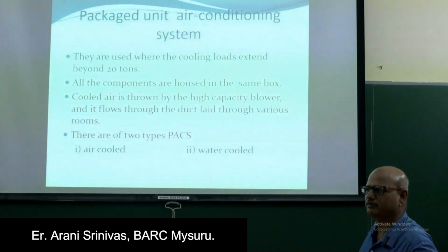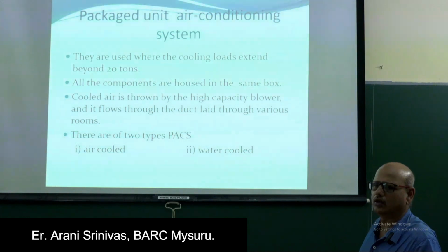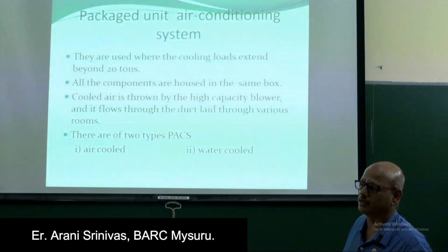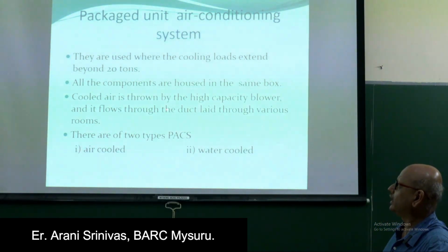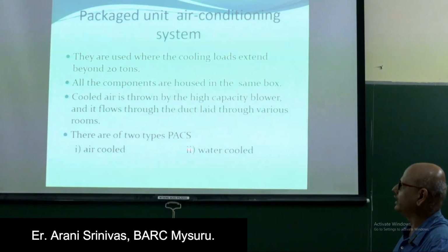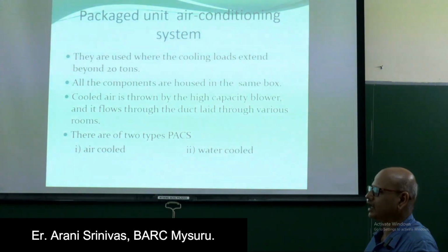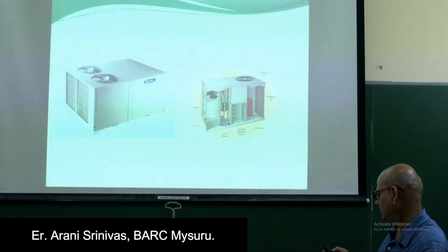So with the blower, we will have a ducting system, as you might have seen in malls and hotels, where ducts come and cold air flows through them. The unit will be kept outside, in a place where there will be no disturbance. The cold air is thrown by a high capacity blower and flows through the ducts to various rooms. There are again two types of package units, air cooled and water cooled. Depending on the conditions, availability of water and quality of water, they will decide whether to go for air cooled or water cooled. This is a typical ducting system.